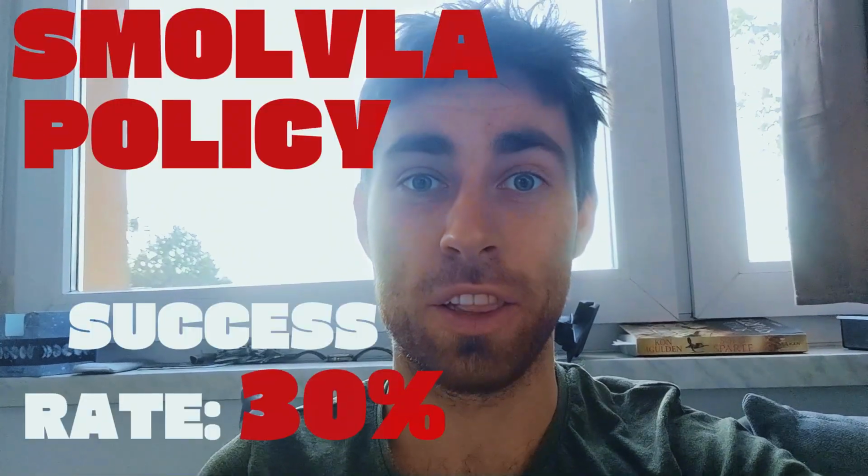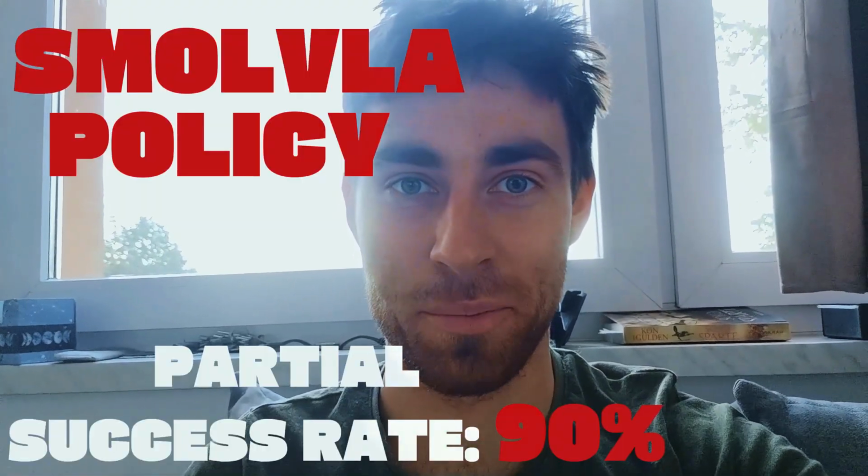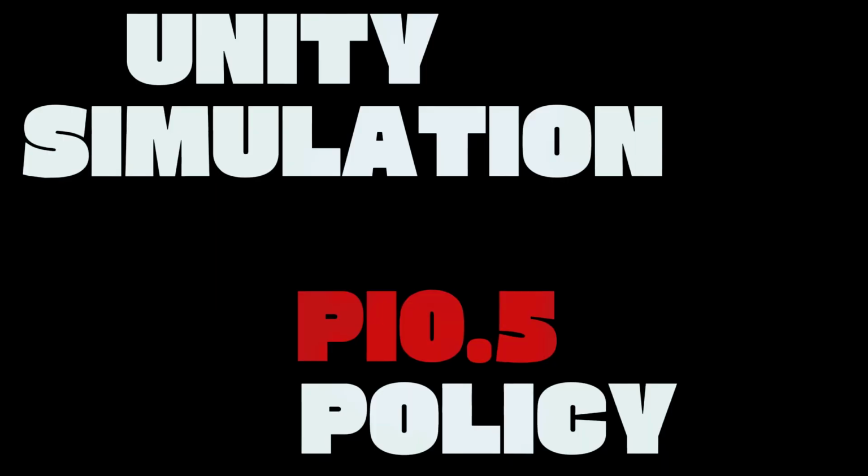So after reducing the frame rate, our SmolVLA model performed much better. It has a success rate of a complete shot hitting the watermelon of 30%. The partial success rate, aiming at the watermelon but not shooting it, is 90%. So it's much bigger than in the case of ACT, but it also has its own cost. The time of calculating a single step for SmolVLA is much bigger, around 90 milliseconds. So definitely, to run that model you need better hardware.